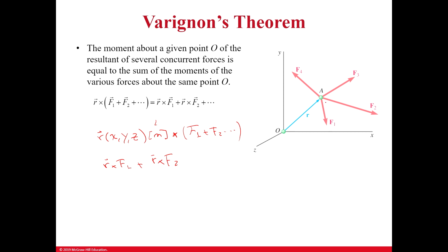So in that case, you can add all the forces together by components. So you can have the components in x and y and z, and add all the x, y, and z components, and at the end you can find the moment at O. So the vector r will give you, remember, head minus tail. It will give you the distance of the force.